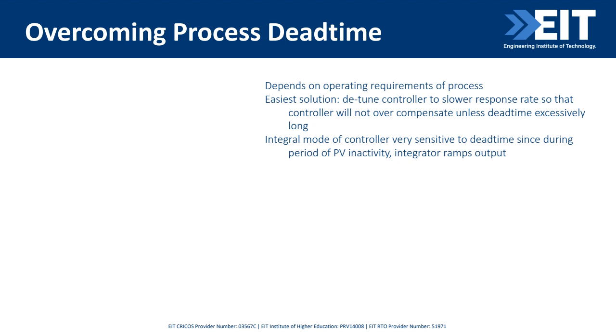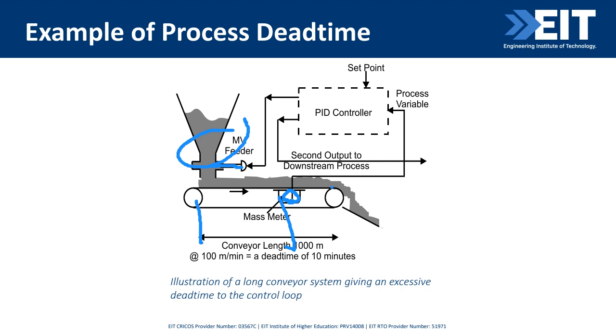What a Smith predictor really does, in essence, and I've taken that slide out because it's quite complex, although I do love explaining it, and we don't have the time to do it, is that it models the process that you've got there, the delay. The Smith predictor strips out the delay. So as soon as you change the feeder from 50 to 55%, your controller immediately reads back through the Smith predictor what that response would have been. So we take the delay out.